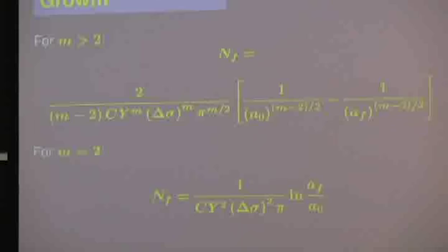So depending on whether the value of m is exactly 2 or a different value, slide number 14 allows you to determine how many cycles it's going to take to go from one crack length to the other. That was our very objective here. It's not linear. It's some form of exponential function. By the time you know your material properties, C and m, you essentially can solve the whole equation. You need to know your stress.